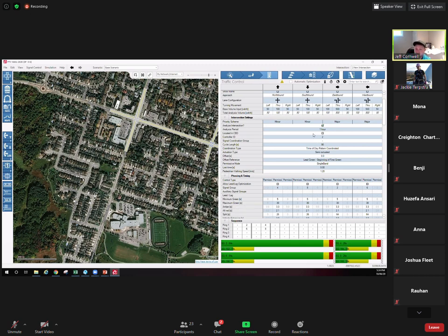And then for anyone who's looking at this intersection settings menu here, the same menu I had on my PowerPoint, there's this option for signal coordination group. So now I can pick Stone Church Road. You have to actually do this for each intersection. I think it should do it by itself, but I guess it doesn't. So you want to click on your other intersection and then change its signal coordination group to Stone Church Road.